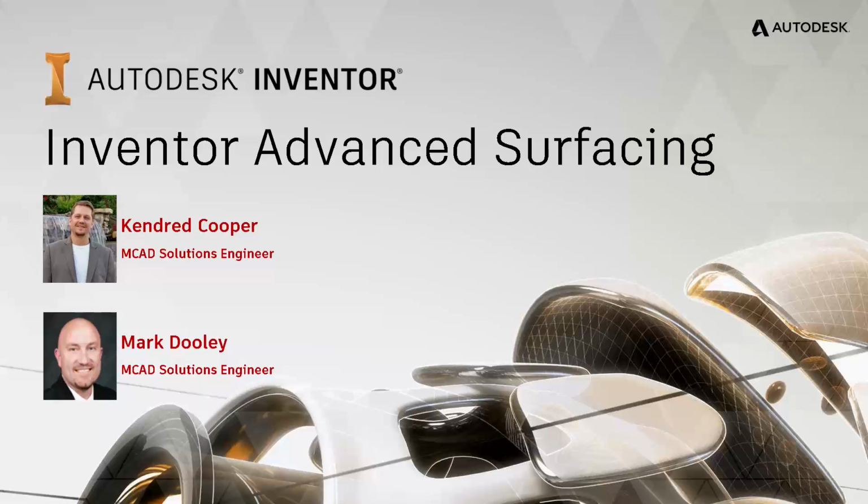It defaults to a transparent display. You can turn that default off. There are no interference detection abilities in an assembly. So if you've got an assembly that has some solid components and some surface components, surfaces will be ignored for interference detection. You also cannot 3D print a model coming out of Inventor that was built as surfaces. A lot of other products, that's what they deal with. They're polygon surfaces, and the way they write the information is a little bit different than the way Inventor writes a surface model.